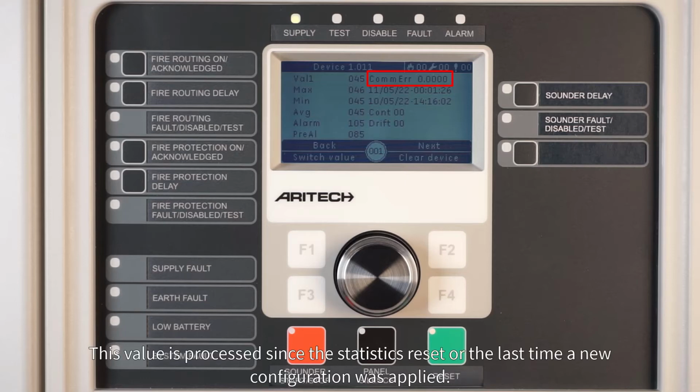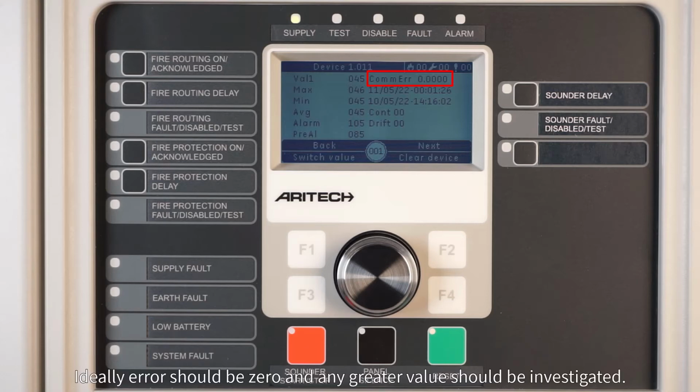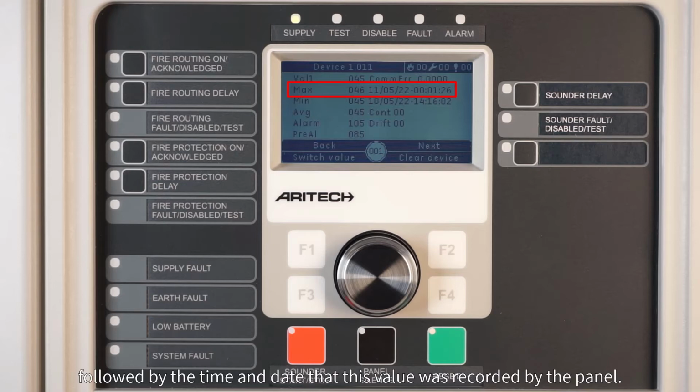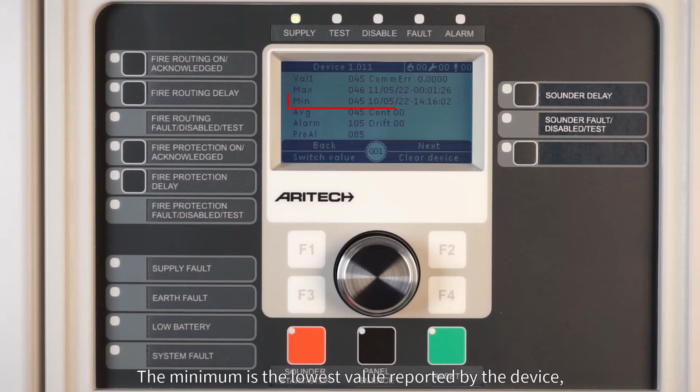This value is processed since the statistics reset, or the last time a new configuration was applied. Ideally, the error should be 0 and any greater value should be investigated. The maximum is the highest value reported by the device, followed by the time and date that this value was recorded by the panel. The minimum is the lowest value reported by the device, followed by the time and date that this value was recorded. The average is the mean recorded analog value for that device.